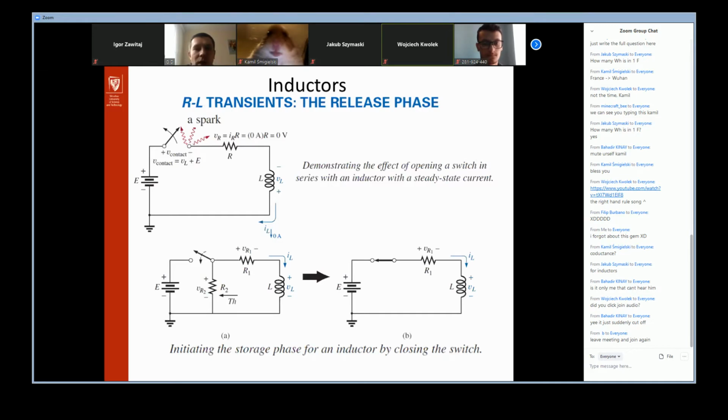It is like the light storm. Yeah, this is the same story. Also, the sparks observed here are, in fact, like the light storm. However, when we are opening the switch, for the first moment the distance between the contacts is so small. So if the air breaks down at 30 kilovolts per centimeter, and the gap is some micrometers, as you see, in fact we'll have a lot of voltage connected across the connectors to get the sparks effect.